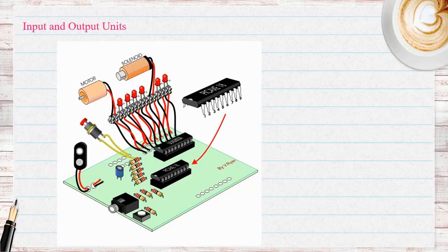To interact with the embedded systems we need input. The input may be provided by the user or by some sensor. Sometimes some systems need more input or output, so the processor selection will be based on I/O. The I/O needs to be configured for input or output based on the provided register. And for that, we need to refer to the datasheet of the manufacturer.